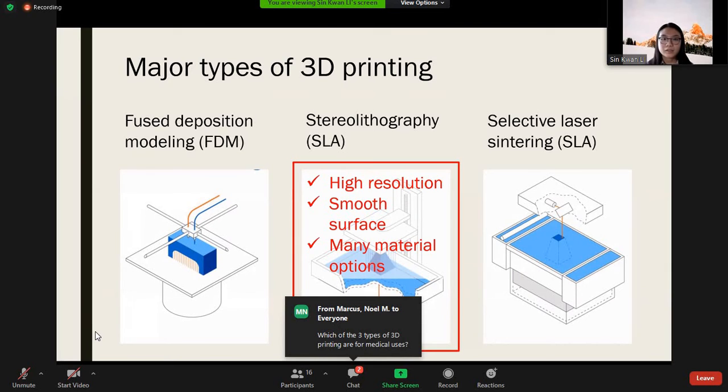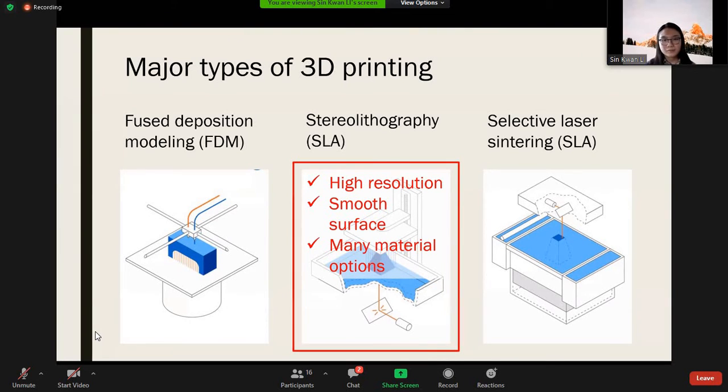But because the technology I just mentioned is quite new, I still haven't found a really valid comparison between DLS and selective laser sintering. So I can't tell which one can print out parts with higher accuracy, but I would say they are pretty similar in that part. When compared with FDM, it's a bit more expensive, but the product produced would have high quality.